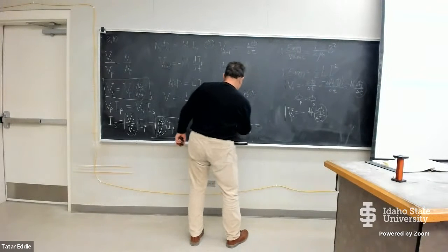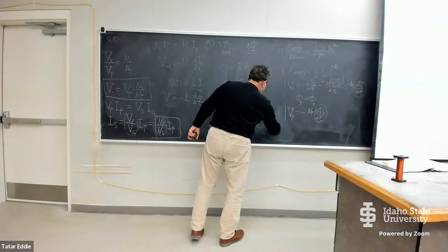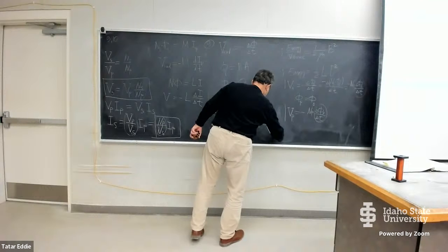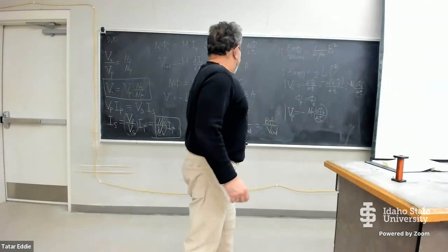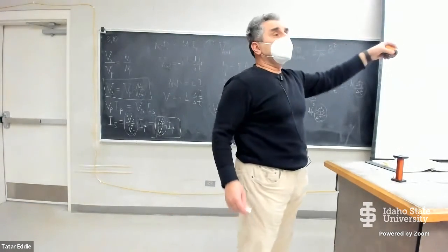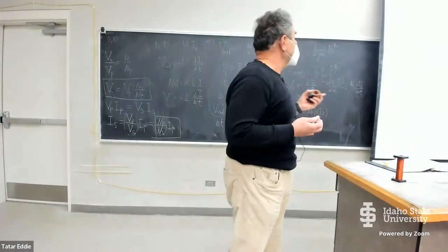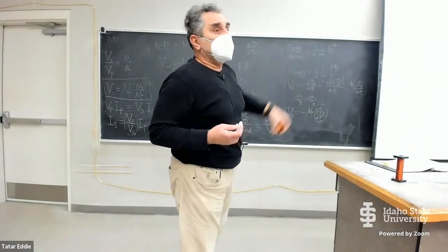So you're going to have magnetic field times area divided by the allowed induced voltage. So you have 3 Tesla multiplied by 0.034 square meters for my version, divided by 0.01.